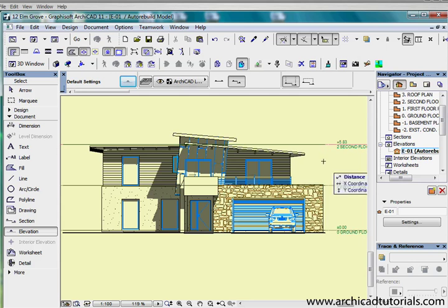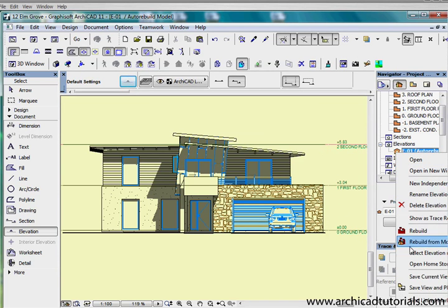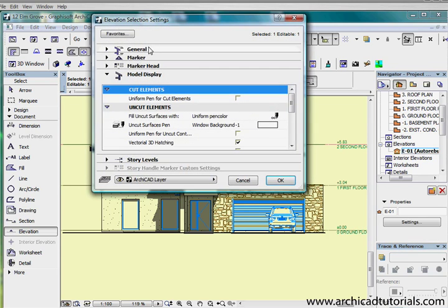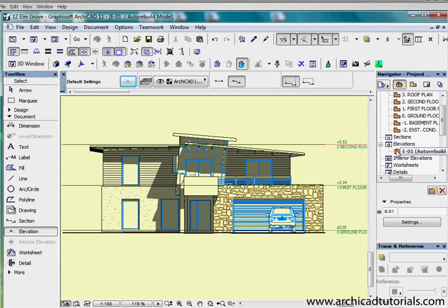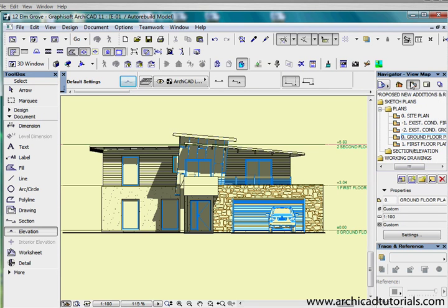And if you save any of these views with any of these settings, we can save them as a favorite. I can also save it in our view map, and it will save all the view settings as well, so it's view specific. So if you've got your template set up correctly, you can virtually do all these drawings with all the different graphical capabilities of ArchiCAD by pushing a button, really.